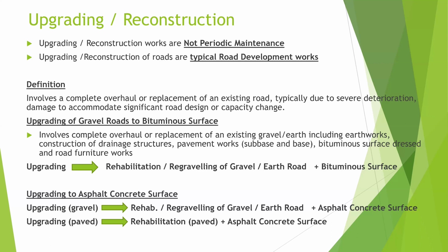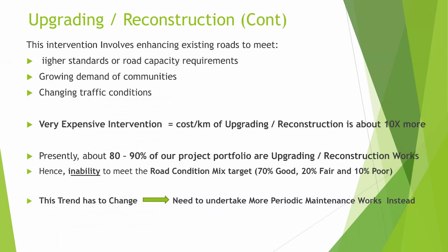Now, you can also have upgrading to asphalt concrete, where the gravel is converted to an asphalt surface road, or you have a BST converted to an asphalt concrete surface. In both cases, we call it upgrading, or reconstruction. Now, this intervention involves enhancing the existing road to meet higher standards of road capacity requirements as the growing demand of communities and changing traffic conditions.